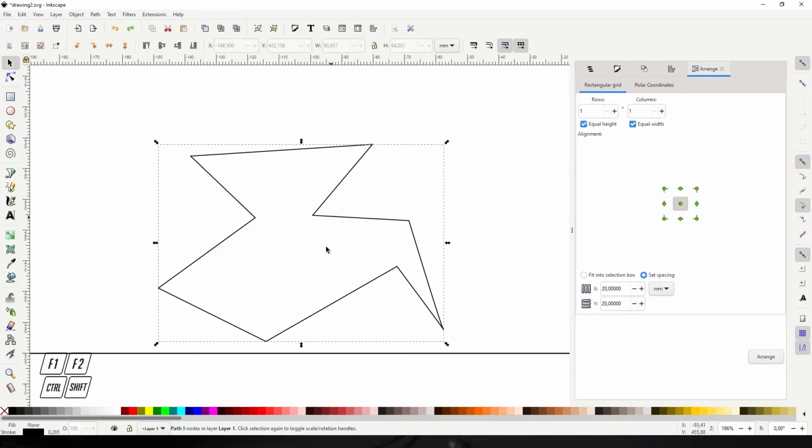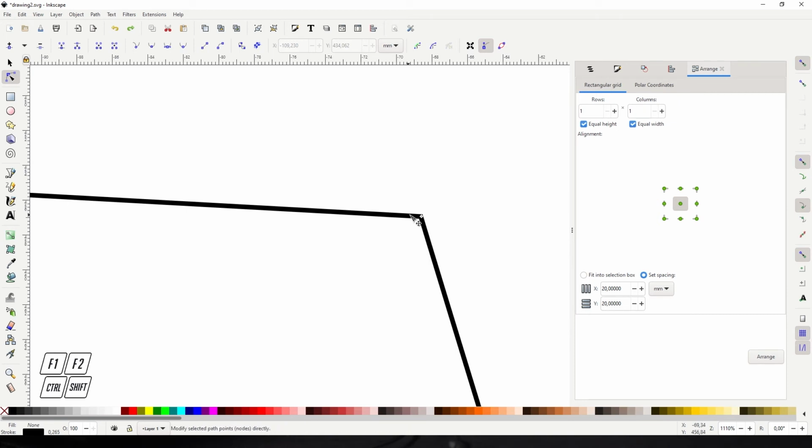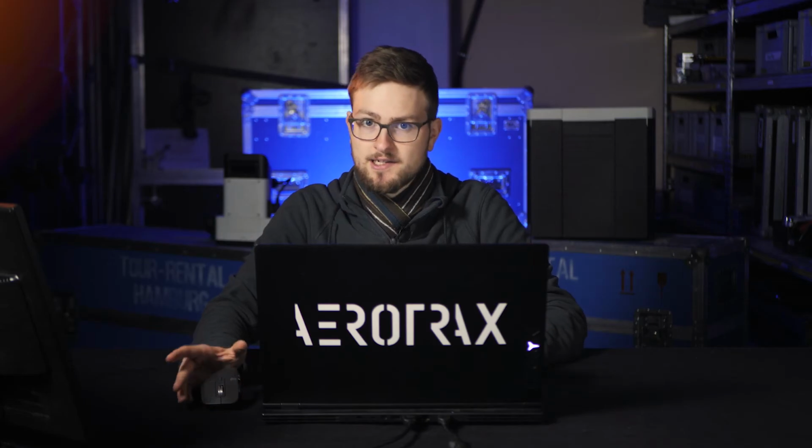The first and very important step is to simplify our shape. Of course, for this one that I just made, it has these very defined vertices here. But as mentioned before, if you import SVGs from other people or if you digitized it from a photograph, then there's quite likely a lot of redundant points in the middle of these lines. And do that by choosing the path simplify command or pressing Ctrl L and doing that as long as it takes, so that the nodes seem more organized to you. And that there aren't like 5 nodes on this short segment of a corner, because it will likely disrupt our